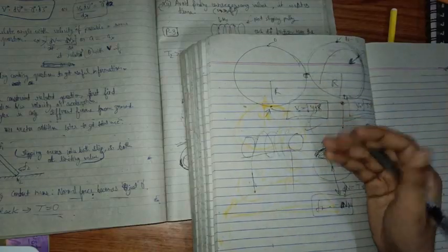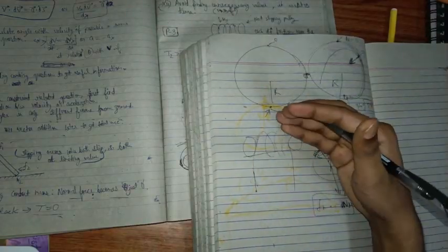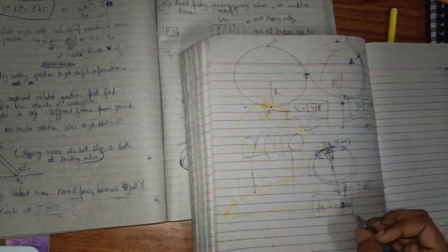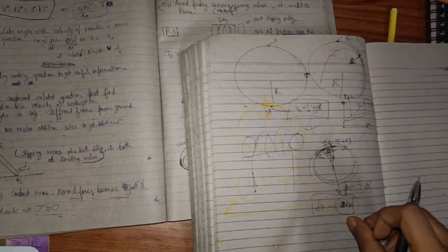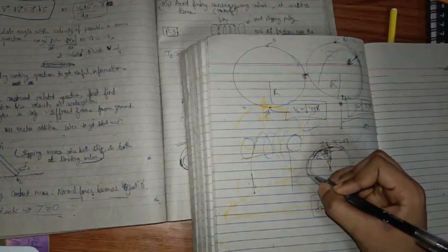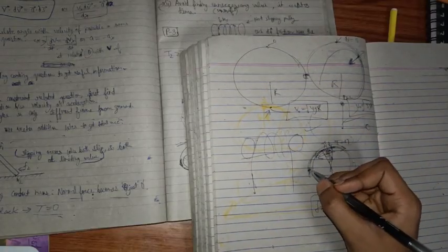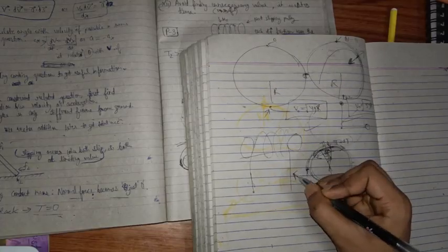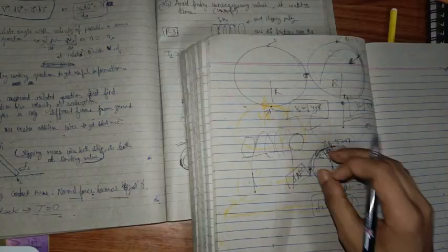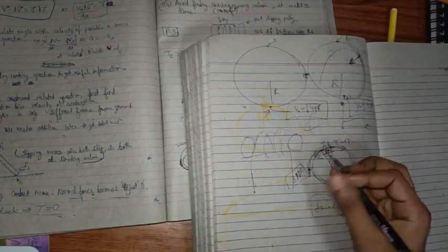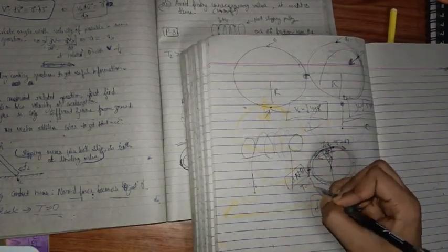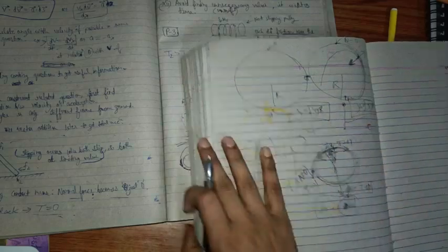will apply some friction and it will reach its peak value, then the length behind it will reach its peak value, and similarly all the lengths will reach their peak value. So all of the elements are providing dN into mu friction, which is their limiting friction, and this limiting friction will act as long as there is no point where the normal force becomes zero. This means the friction force will be reaching its limiting value at each element, at each point, as long as the normal force does not become zero. Means as long as the tension does not become zero, the frictions will reach their maximum value.